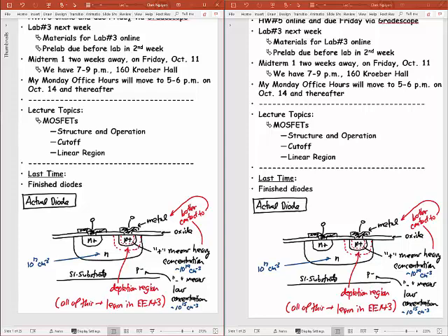And of course this is a diode, so that's a depletion region. And the depletion region, as you saw in the last lecture, is where all the action occurs. So let me just add that. I've got all this structure here, but everything is really happening right around that P plus junction, because that's where the P and the N really meet. And so that's where the diode really is.